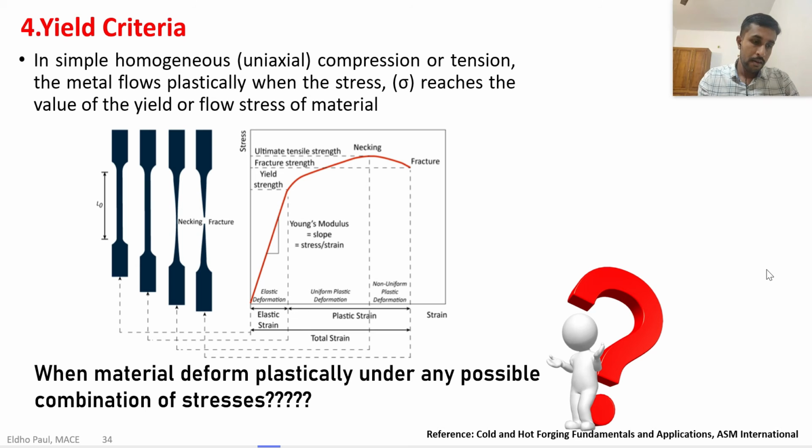In the last lecture, we discussed the stress strain relationship. For any material, we can draw a stress strain relationship by conducting a UTM test. For example, in this figure, we can see a specimen subjected to uniaxial tension, and the corresponding stress strain graph is drawn here. And here we can see the first specimen. It is loaded within the elastic limit.